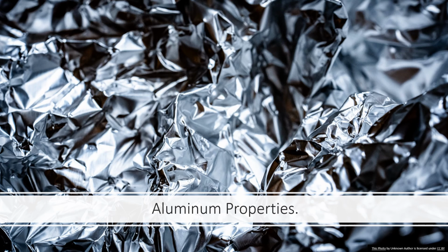The properties of aluminum: it's a ductile silvery white metal, usually with a dull luster owing to a surface film of aluminum oxide. Aluminum is lightweight, approximately 1/3 as much as an equal volume of copper or steel. It is corrosion resistant and is an excellent conductor of heat and electricity. It reflects both light and radiant heat, and is non-magnetic and does not readily absorb neutrons. It can be safely used with food and medicine and can be formed by all known metalworking processes.